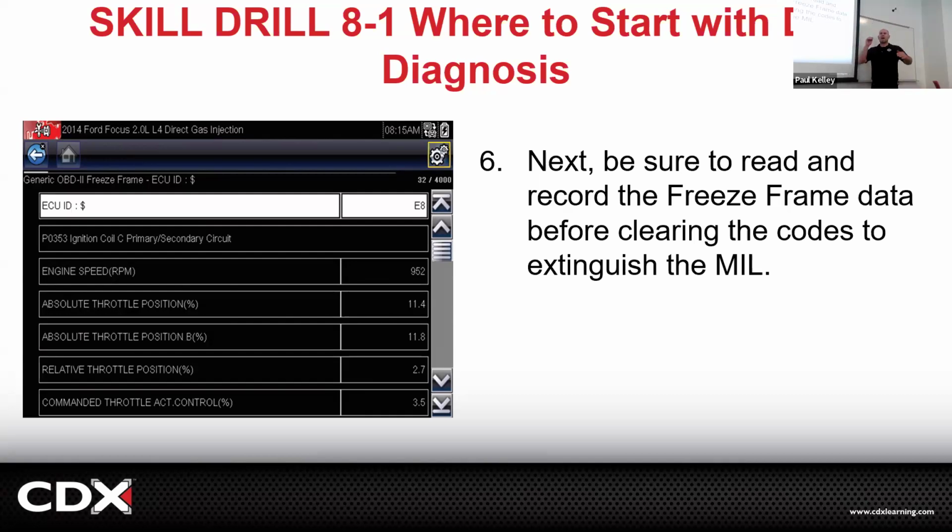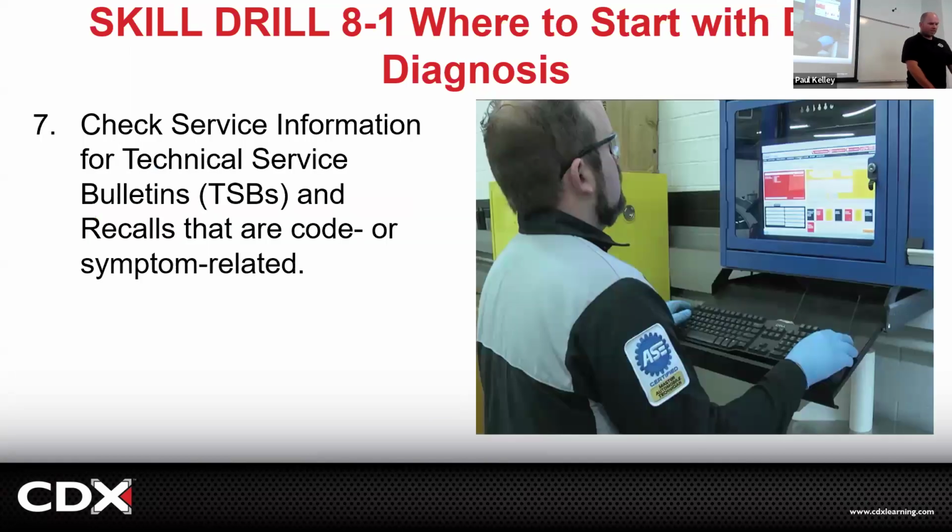Okay, so if your battery was slowly dying, a lot of times your voltage going down can set a lot of codes that aren't really codes. So if a car comes in with a whole bunch of weird codes, it might not exactly be because of the drive-in, but sometimes their battery was dying and it sets random codes. I might clear all that out, see what comes back. But I would record it first though. Okay, that's kind of the lesson, right?